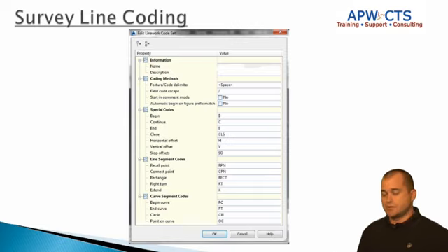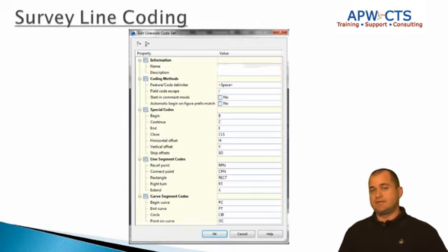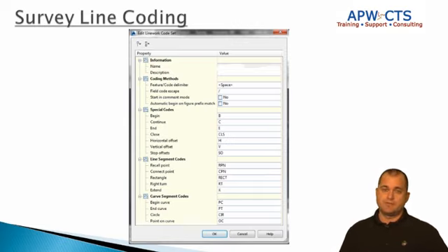Now, you also want to keep in mind that just because you can doesn't mean you should. There are certain codes that, while they look really good on paper, sometimes don't work real well out in the field because you have to remember and recall a bunch of information. So I find that if you use a noting feature out in the field and tell it that it's a right turn, see sketch, then you have a sketch that has your dimensions on it. When you edit the file before you process it, or after you process it, you actually use these same key codes or line codes when you're editing the fieldbook file as you process your data in the office. So some of this is mostly out in the field, but there are some office procedures you also want to know when using field to finish or line coding inside of Civil 3D.